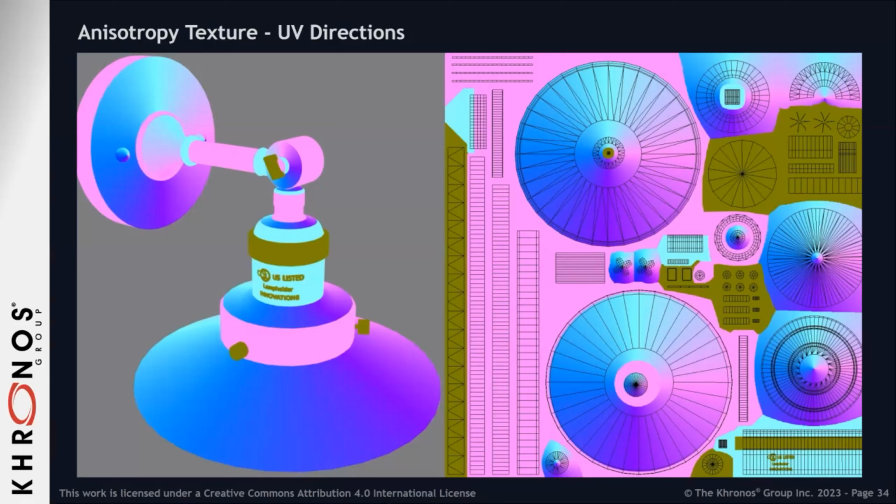So some UVs are vertical, they're colored in pink there, and some are horizontal, so they use the light cyan color. The brush pattern is vertical on the pink ones, so we want the anisotropy to be perpendicular to that. And then on the light cyan ones, well, those are horizontal UVs, but the grooves are actually running vertically. Again, the grooves are running horizontal for those blue areas. So we'll want the anisotropy to go vertical.